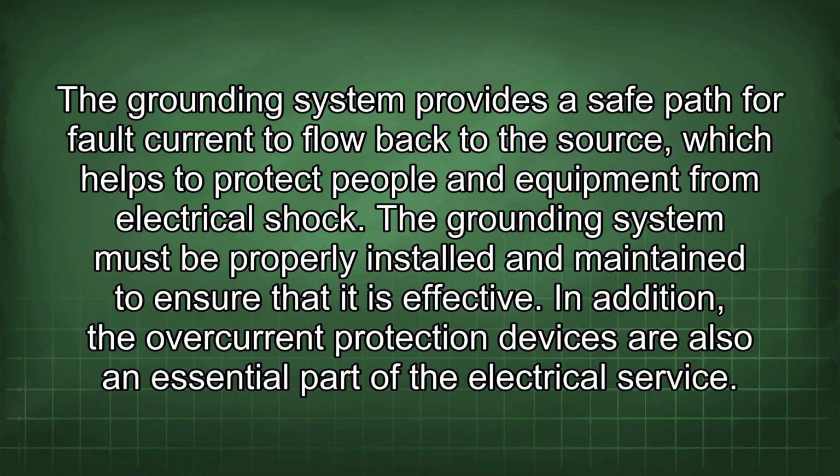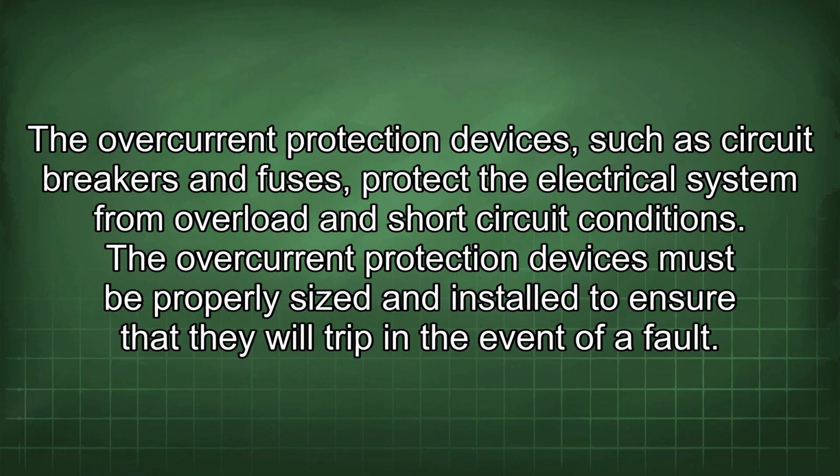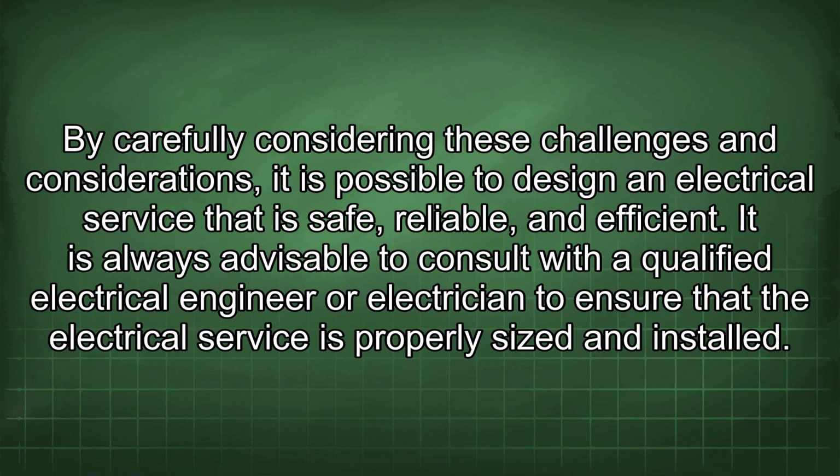In addition, the overcurrent protection devices are also an essential part of the electrical service. The overcurrent protection devices, such as circuit breakers and fuses, protect the electrical system from overload and short-circuit conditions. The overcurrent protection devices must be properly sized and installed to ensure that they will trip in the event of a fault. By carefully considering these challenges and considerations, it is possible to design an electrical service that is safe, reliable, and efficient. It is always advisable to consult with a qualified electrical engineer or electrician to ensure that the electrical service is properly sized and installed.